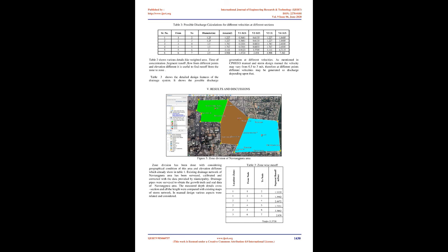The existing pipes of the city from zone 1 to zone 3 carry maximum water, and in the rainy season the storm pipes and roadways both carry the high runoff. This occurs because the inlet is insufficient to carry the initial discharge, which truly affects the capacity of the pipe from zone 1 to zone 3.